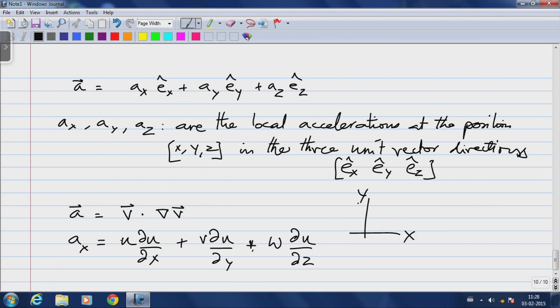So, if I have a body only moving in a plane in such a fashion, if at these 2 locations the velocity is instantaneous and is tangent to this path locally at that point, the rate of change of the x velocity, meaning u, in the y direction, du dy, causes an x component of acceleration.